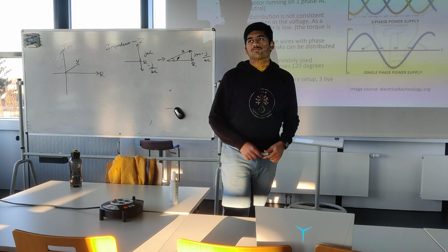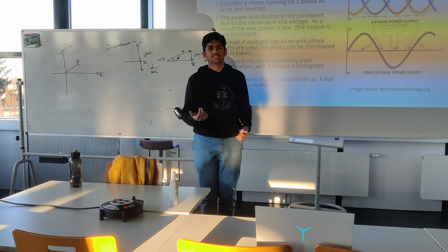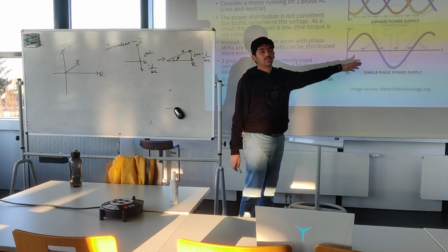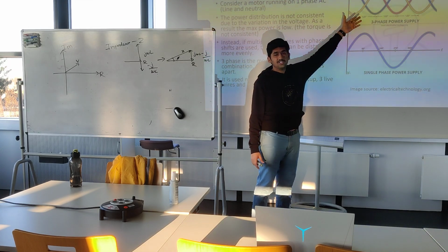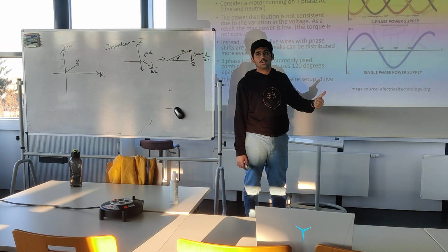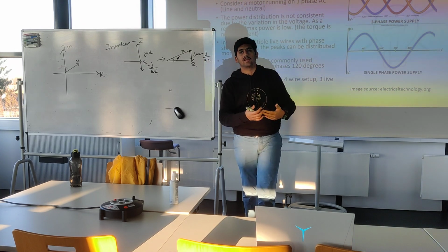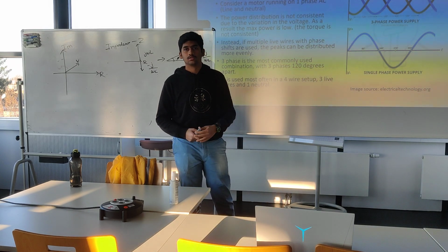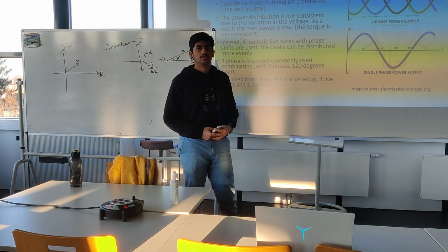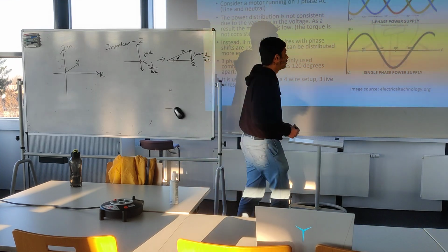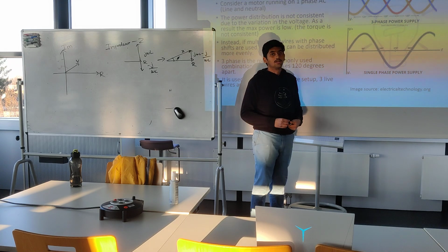Three-phase AC. So why do we use three-phase? Why not just single phase like here? What disadvantage could be there? Because if you have three phases, it means you're having three live wires plus a neutral wire, and you have to transmit this over long distances. Why would you voluntarily take more wires, when you can do with less? It provides more uniform flux.